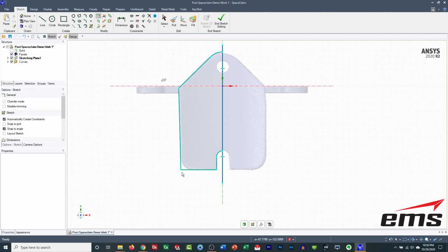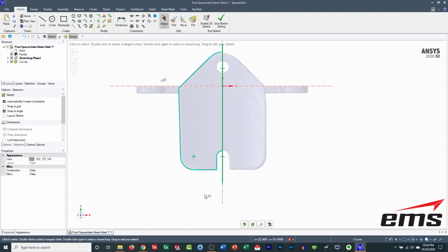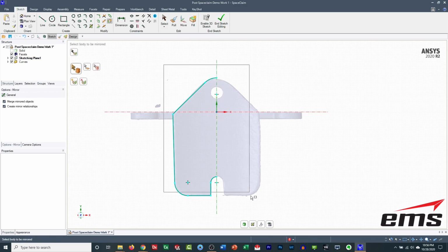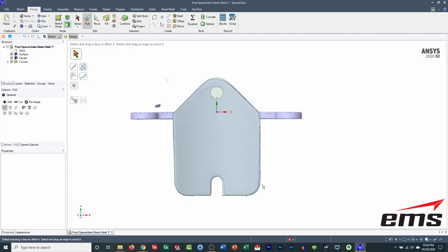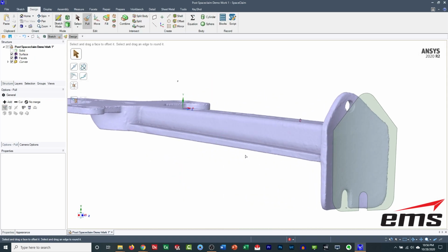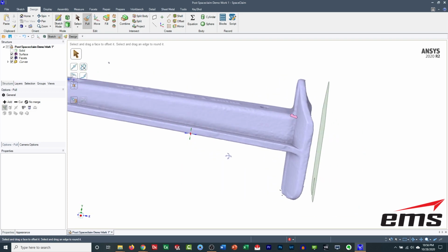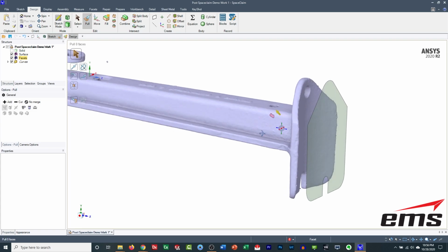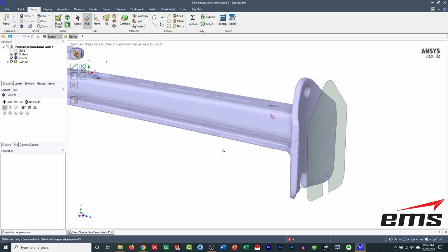And let's go ahead and put this radius in here. This is a large enough radius. We'll go ahead and put it in. And then last but not least, we'll get rid of our line. Okay, so we'll go ahead and mirror that over about our symmetry line. There we go. Okay, so that's our first sketch, and we'll just leave that there for now. And then we're going to need to make this shape and then kind of intersect the two. So let's work on that next.